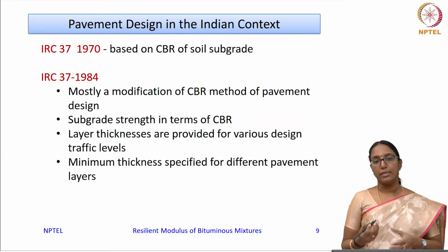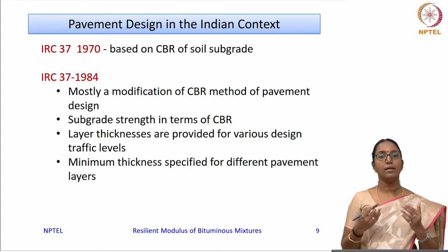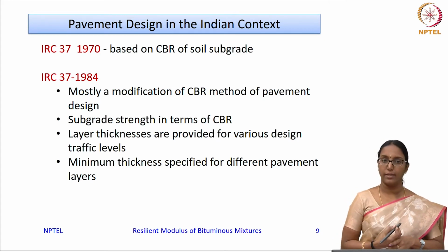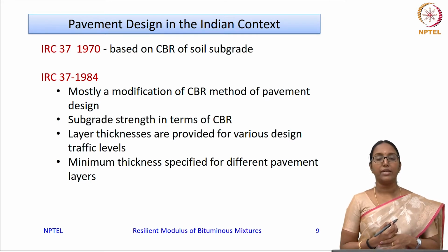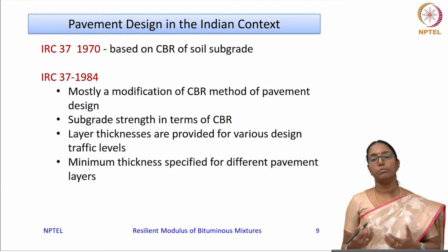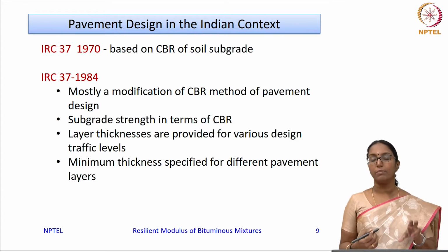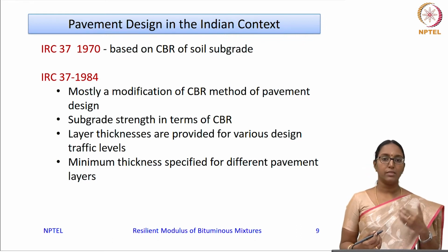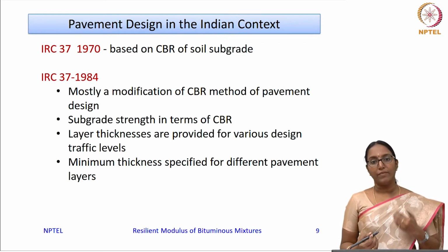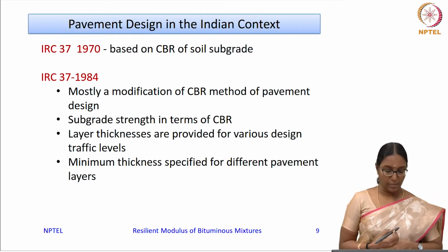Now coming to the Indian scenario, we have been designing pavements based on IRC 37 standards developed way back in the 1970s. IRC 37 started with the design of flexible pavement layers on the basis of the CBR of the subgrade, or the subgrade strength is taken as a parameter for evaluating what the layer thicknesses should be.